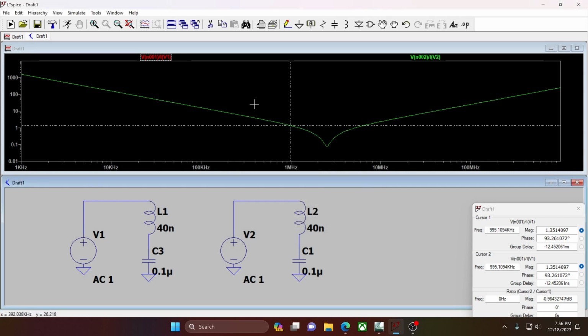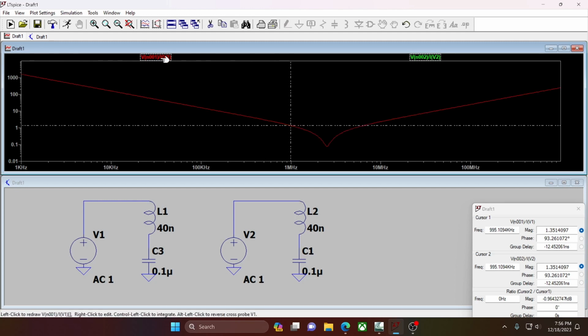So on the top, what we have going on here are two graphs. Right now they look the same. So red is going to be our control. This you might recognize as an impedance graph. Over here is our impedance measured in ohms. Down here is our frequency. So just a crash course. When it comes to reading these, capacitance dominates all the way here on the left. Inductance dominates all the way here on the right. And when they come together, it's a resonance. Now we have all that, we can play.